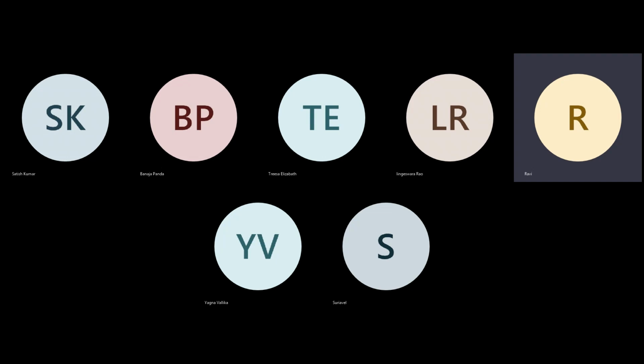It will enable the timing and check. Hey, this guy is violating, so there is not a possible location. Then it will go and alter. That is your global route phase 2. Okay, second phase. So you will see 3 or 4 phases happening. In each phase, there are 20 steps, what I told you, right? How it is breaking down in a Monte Carlo technique.